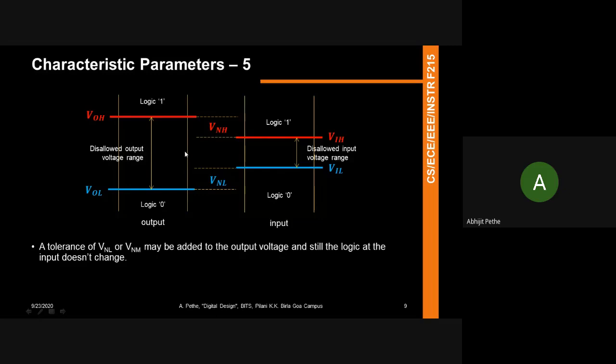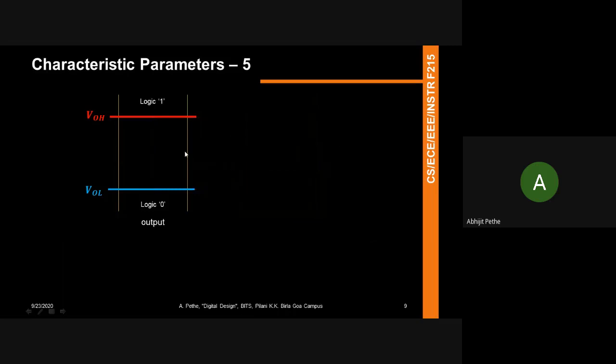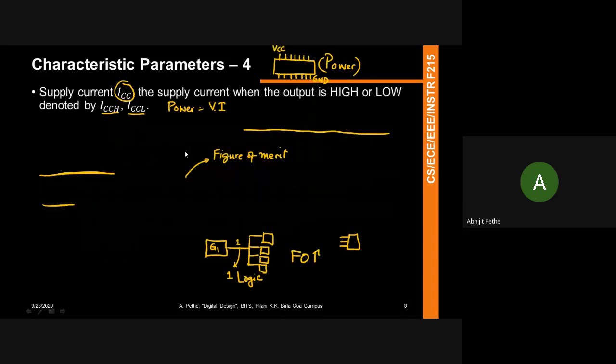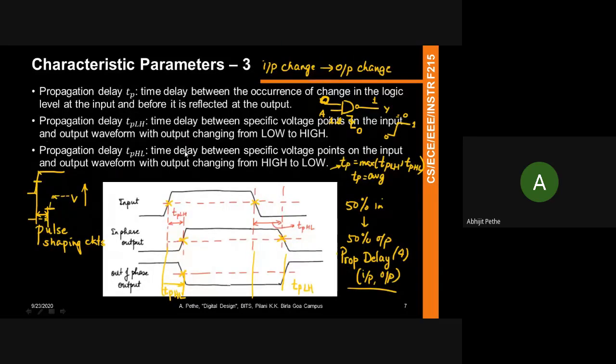Abhishek, how do we change input from high to low linearly as shown in the VT curve? It's not a question of changing. That's how the voltage normally looks. If you're going to do a circuit design, this is how your voltage will look when you plot the input output characteristics. In reality, it is not linear. It is curved right here and it is curved right here, and that depends on the transistor characteristics. Okay.